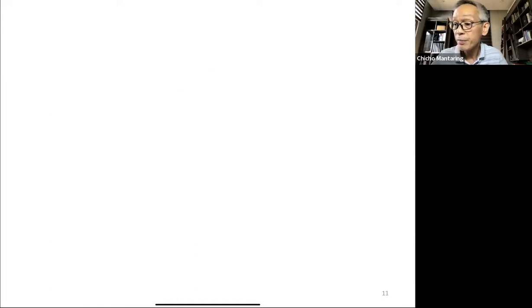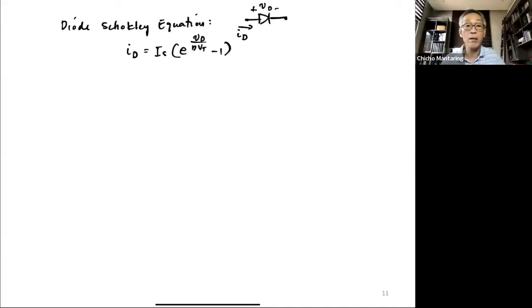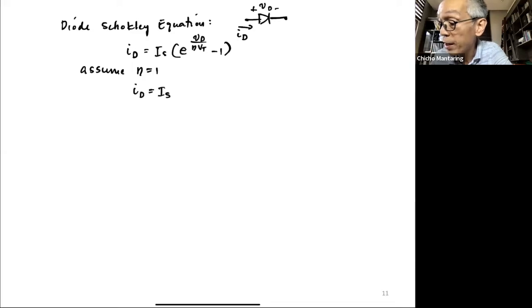Okay, now recall the diode-Shockley equation. Okay, so we said that your diode current, so this is I sub D, and then this is V sub D. We said your diode current is equal to your reverse saturation current e to the V sub D over eta V sub T minus 1. Okay, let's assume that you have a good quality process and that eta is equal to 1. So I sub D is just equal to I sub S e to the V sub D over V sub T minus 1.